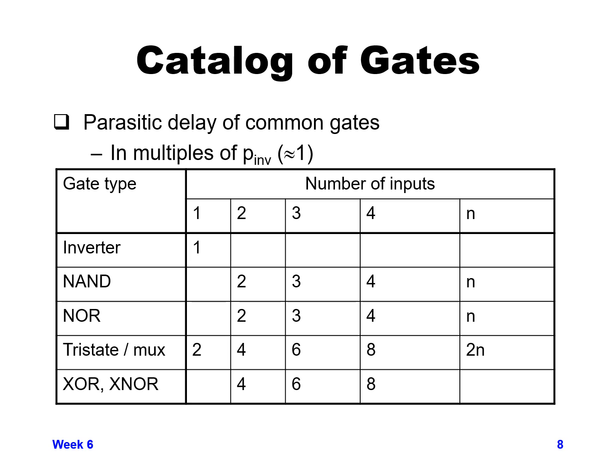So keep in mind, different gates behave differently. In some, the logical effort goes up per number of inputs. In other ones, and in most gates, the amount of parasitic delay goes up with the number of inputs, as well as the logical effort going up. So it just depends on the type of logic that you're dealing with. But definitely make sure you understand logical effort and parasitic delay, because we'll be using that in all of our examples going forward.